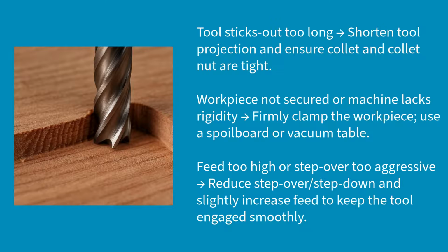Another one might be that your workpiece is not secured, and so you want to make sure that your material is firmly clamped on your workpiece. If it's moving, that can cause a bunch of issues, so you want to make sure that you're clamping well. And then the other is that your feed rate is too high or your step over is too aggressive. Try reducing the step over and slightly increase the feed rate to keep the tool engaged smoothly. You just want to make sure that you're checking those things and doing that.